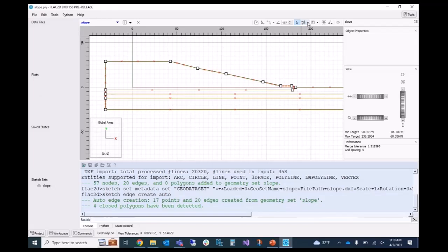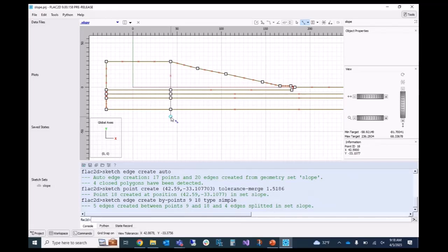So all we're going to do is go over here and choose the line tool, and then click on these points on the top and draw vertical lines down. If you hold down Control, it makes a vertical line. It doesn't actually matter if it's perfectly vertical. And it's OK to go past the end of the bottom, because we can just delete these at the end and get rid of those little hanging bits.